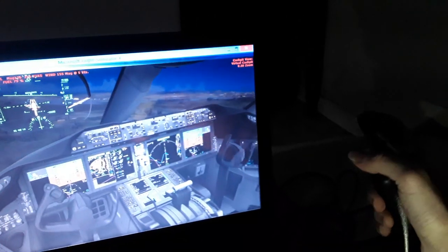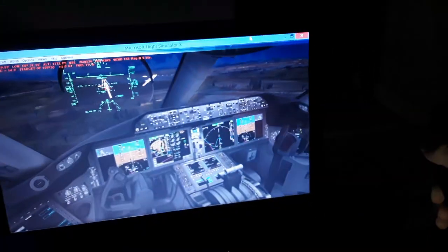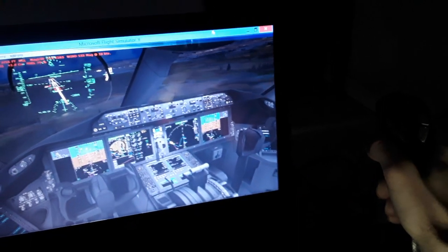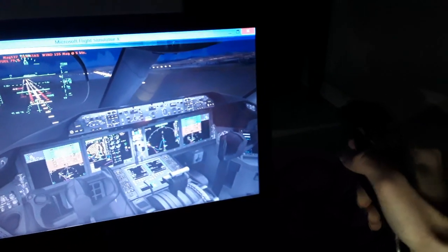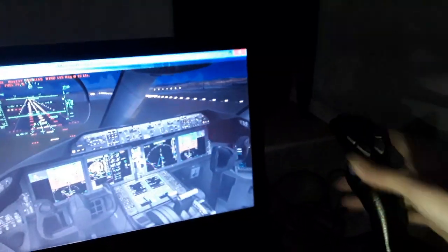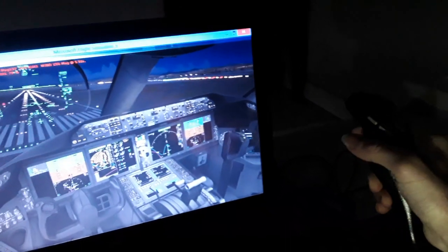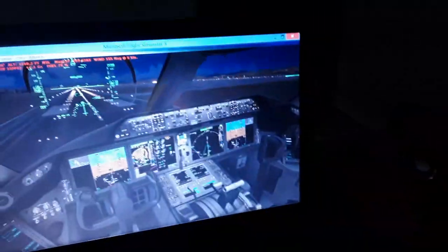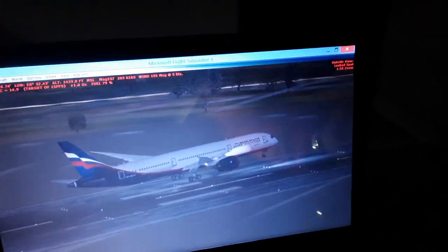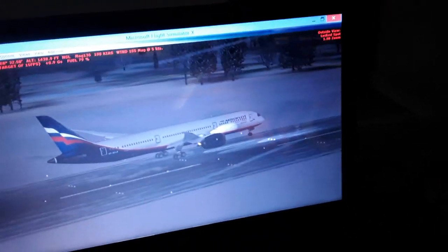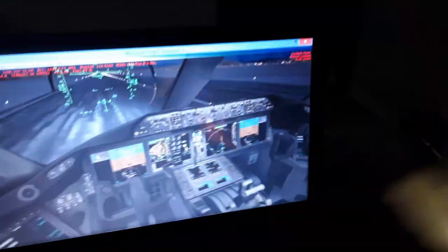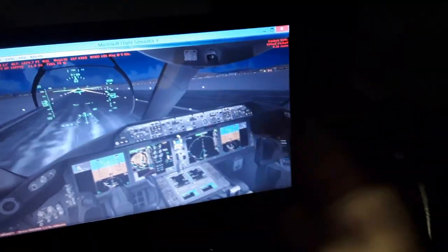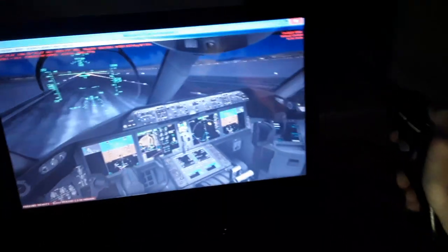So we almost reached the approach and landing over here. Align with the runway heading, side wind and wind gusts. We use the rudder pedals. Use a little bit more idle thrust for the touchdown over here. So we're going to have the flare, as you can see, a beautiful flare over here, idle thrust. So touchdown, parking brakes, thrust reverse over here, reverse thrust and parking brakes. And we are slowing down the aircraft, as you can see.